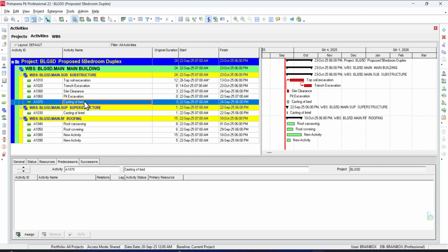So I'm going to share a BOQ with you. You are going to use that BOQ to create a basic activity list with its WBS for that project. A very simple project, not a big project, just a gatehouse. So you prepare the WBS, the activities, the durations, and you assign the relationships.